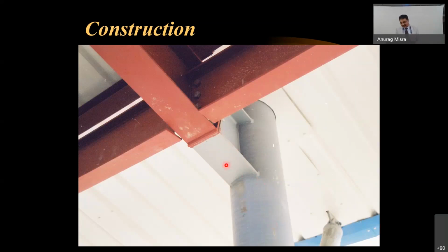So you can see how we deal with that when this is a circular column. Making a connection to a circular column is not a very easy task. So you have to come up with an engineering solution. So a small beam, a bracket, is fixed, which is welded in the factory, and the connection is provided maybe 300 mm away from the member.